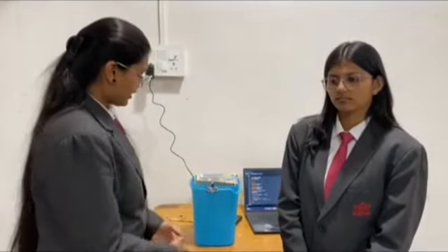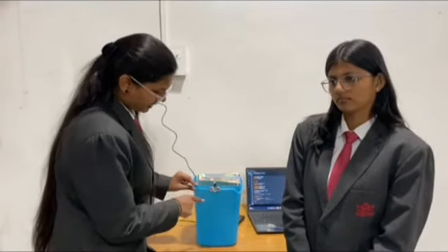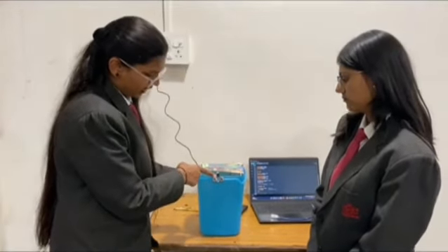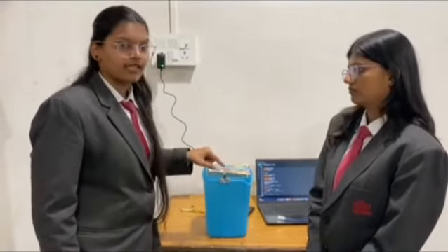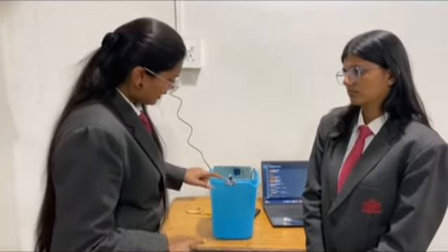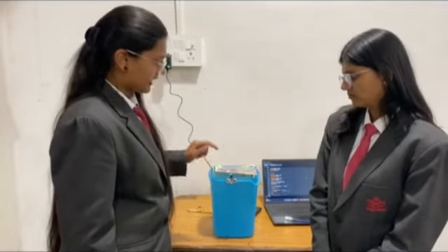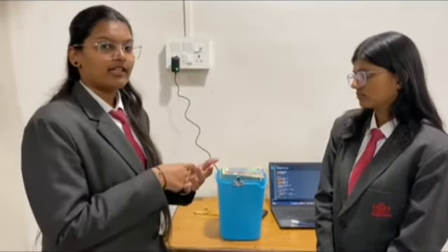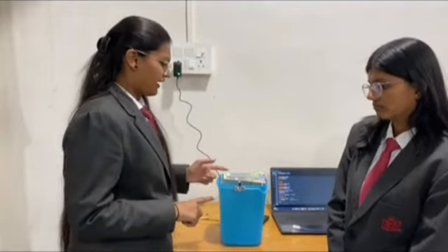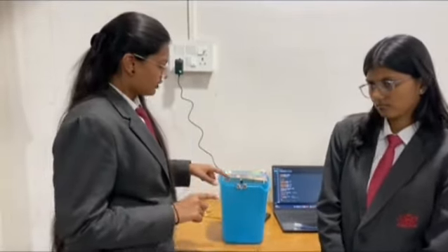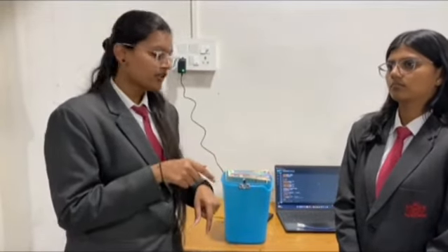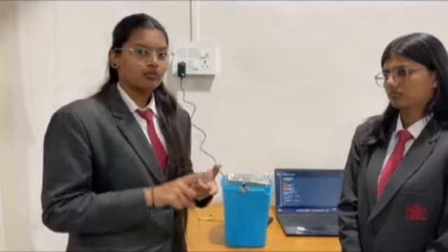Talking about the connections, as she has told, in ultrasonic sensor we have 4 pins: VCC, trigger, echo and ground. VCC of the ultrasonic is connected to the 5-volt of the Arduino Uno. Then ground of the ultrasonic is connected to the ground, in which we have taken the breadboard. As Arduino has only one 5-volt supply, we have taken the help of breadboard and given the 5-volt supply through the breadboard to both ultrasonic